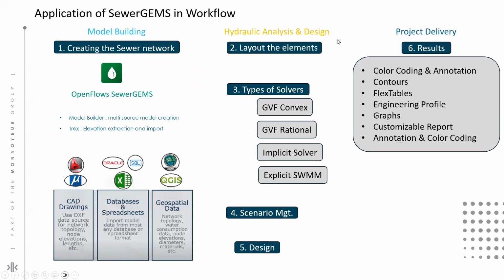How SewerGEM could help to follow that workflow that we generally use during the project area. So the first thing is the model building, as I discussed before. So creating the sewer network, you have the data. You must be having the data in the CAD format, or you have the DXF format, or in the format of MicroStation. You can integrate that data with the help of Model Builder or the multi-source model creation tool within